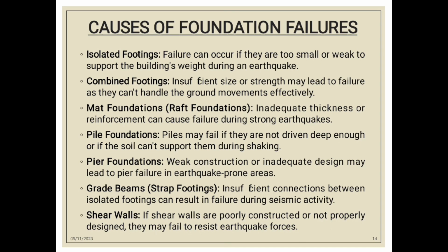Pile foundations: piles may fail if they are not driven deep enough or if the soil can't support them during shaking. Pier foundations: weak construction or inadequate design may lead to pier failure in earthquake prone areas.